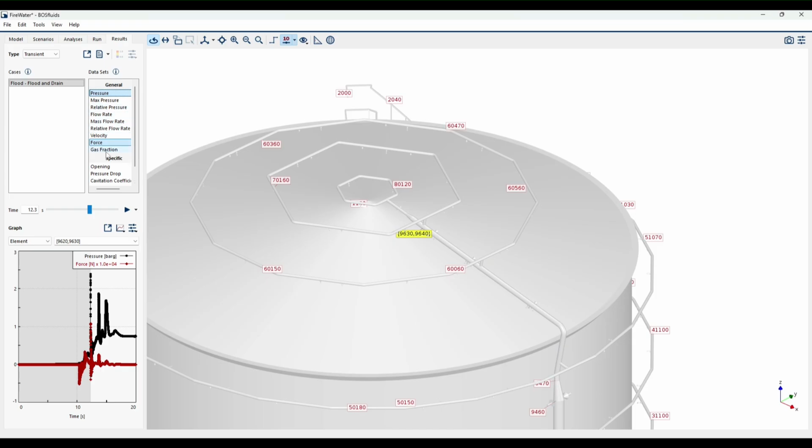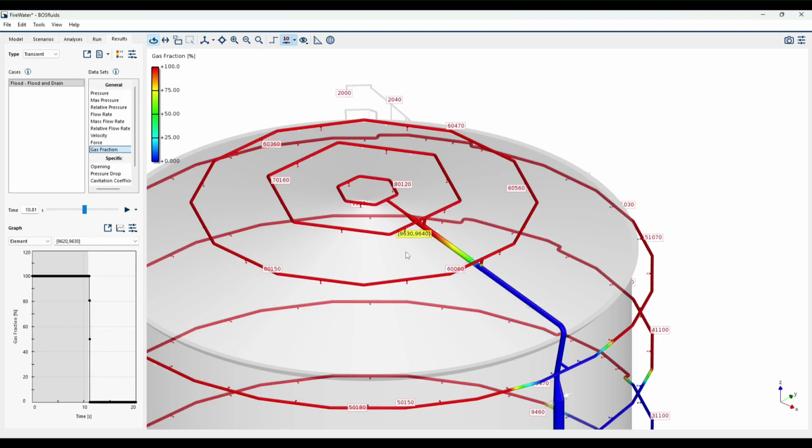So to check that, what we can do is also add the gas fraction. We can see that the gas fraction passes a little bit before, so we will select here. And we will check for now just the gas. So we can see that here, at this moment, when the gas passes through this point, there are not that many forces. But while this continues, there is a moment where these ones kind of have an impact, right? These two different cross sections of liquid or columns of liquid impact between each other,